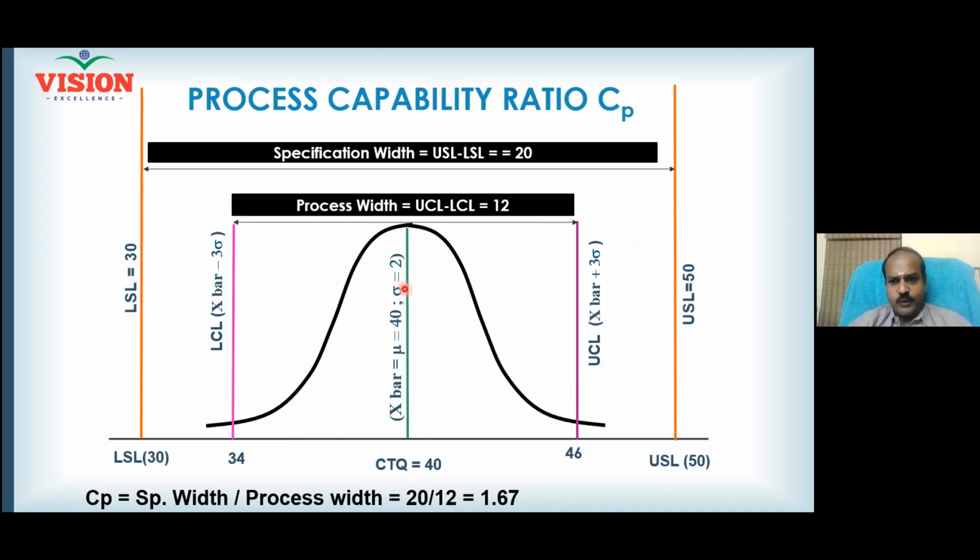You wanted to understand how good your process is. So you picked up some data from the process and calculated X bar. I'm sure you know how to calculate X bar, right? You collect the data and calculate X bar. X bar is found to be 40. When the calculated average is found to be 40, what is your inference? Can one of you tell me now? It's a central line, sir. Process is centered correctly on the target. Can I say like that?